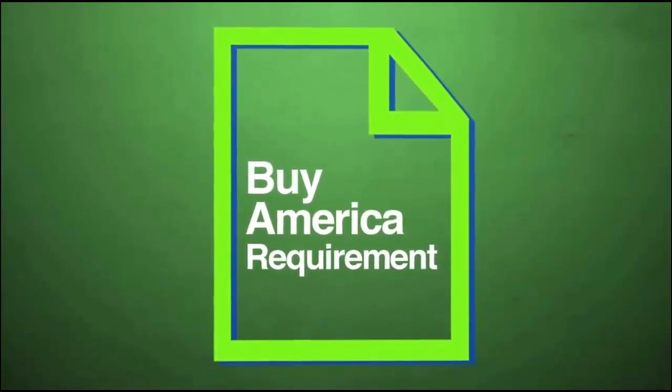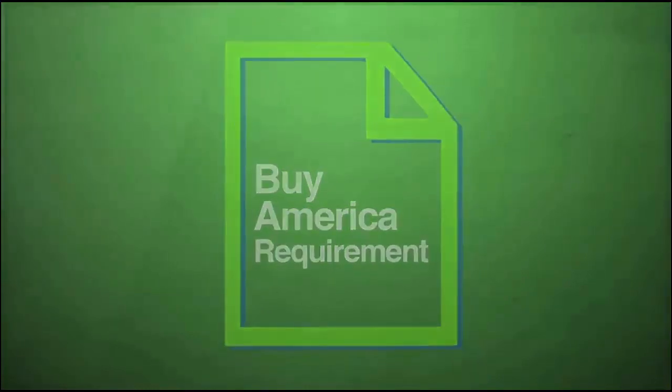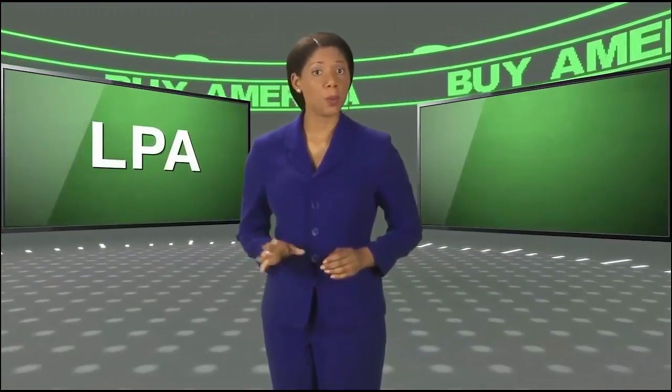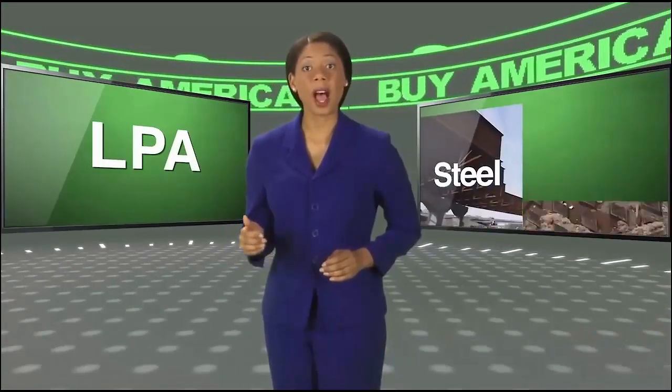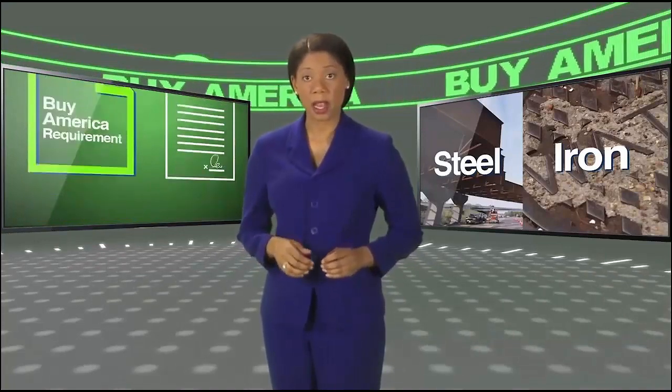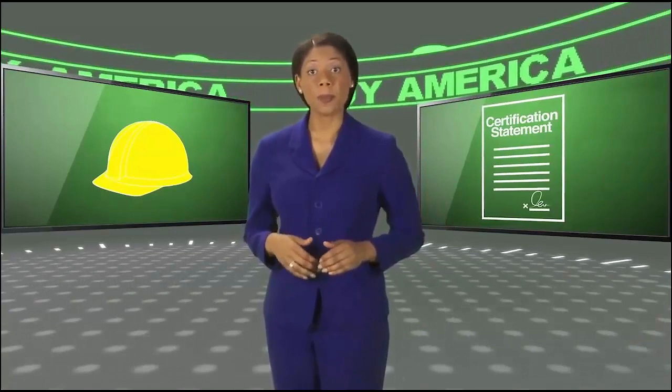Such products should not be installed on a federal aid project. As the local public agency, or LPA, you must confirm that all steel and iron products meet the Buy America requirements before the contractor installs the products into your federal aid highway project. Contractors must provide a signed certification statement regarding the manufacture of the iron and steel products to meet Buy America requirements.